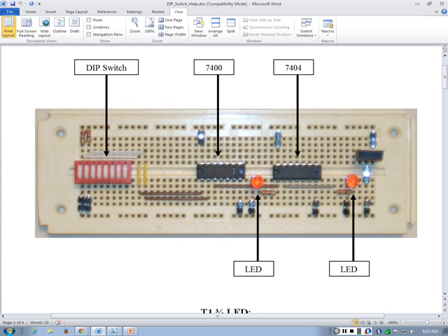So whenever you are using switches, here you have to run a resistor. Do you see there is a resistor? It's 220, okay? In most cases in this class it's a 220 resistor, which we use between the switch and voltage 5, and then you run a wire here to short it. For each and every switch you will be using, you have to do this. We are using 2 switches here, so that's why we did it for only the first 2 columns.